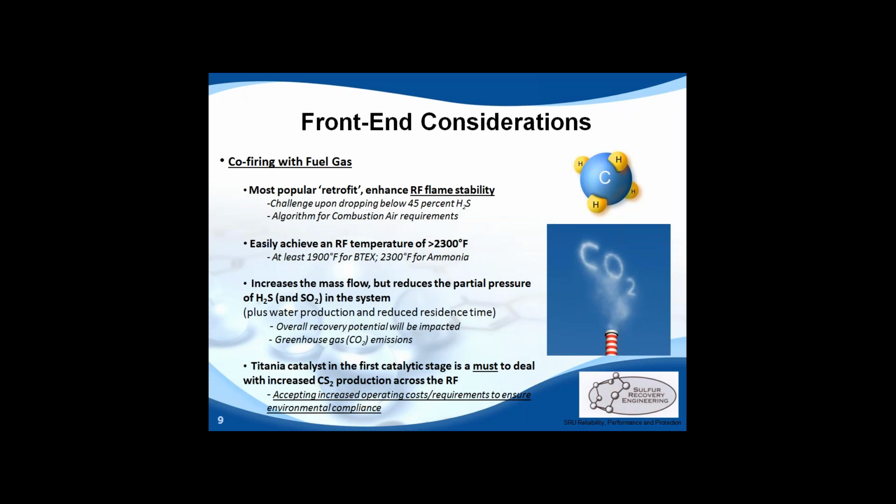If we're at a refinery, the sour water acid gas feed stream typically contains equal parts of water, ammonia, and H2S, so 1/3 water, 1/3 ammonia, 1/3 H2S. We need a little more temperature to best promote the complete destruction of ammonia.